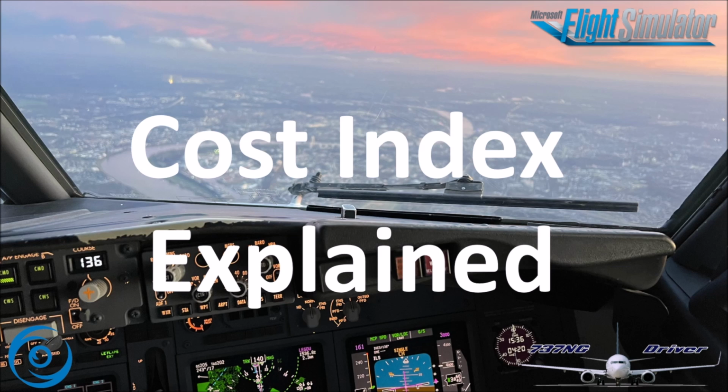In the operation that my airline does, we're operating a cost index of around 10. And in general, our flights are in the region of approximately an hour and 20, with a lot of flights in the region of approximately 2 hours as well. Now, if we're running really late on schedule, then we can contact our operations department and they will evaluate if it would make sense for us to get a cost index 100 flight plan.